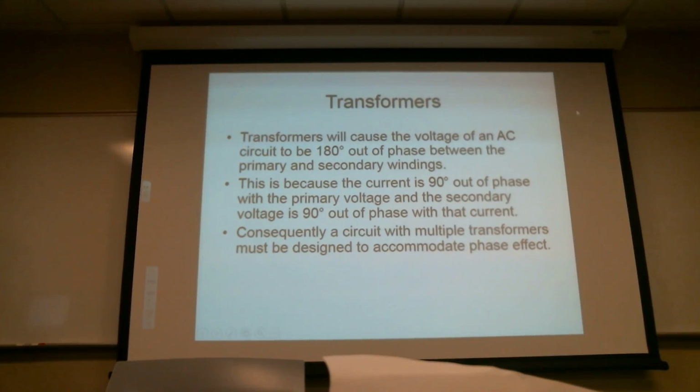Most of the time within a building or within a device, it's not too big of a problem. Where it becomes a problem is when, like for the college, you have an entire ring of 3-phase power going all the way around. And then I jump power from here over to the tennis lights, but then I have a backup power source coming to the tennis court lights from another place that's out of phase with what's happening here. Well, if I end up having both of them interconnected, now I'm going to cause a problem, right? I might have lights that actually randomly flicker on and off, do all kinds of weird things. You don't see this be a problem until you get into more complicated systems.